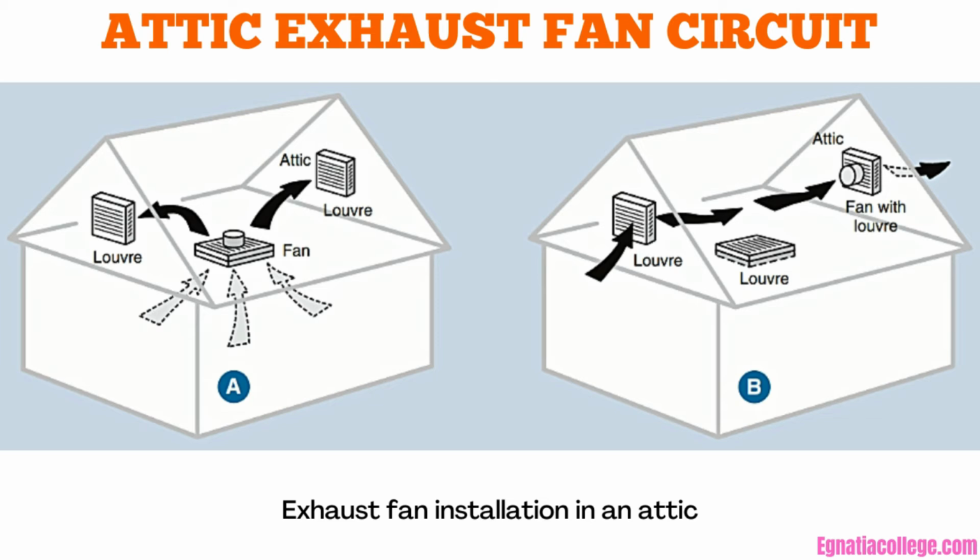The exhaust fan in this residence is connected to circuit A10, a 120-volt, 15-ampere circuit in the main panel utilizing number 14 NMD90 cable. The derating factors in Table 5 must be applied because of the high ambient temperature in the attic. Exhaust fans can also be installed in a gable of a house, see Part B in Figure 16-13.